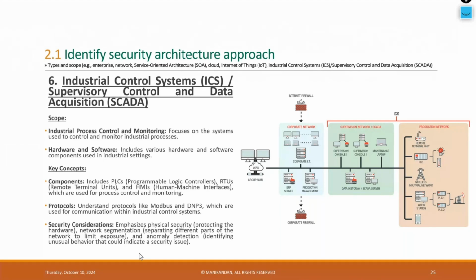What sort of measures shall be taken in Wi-Fi? When we are talking about industrial Wi-Fi, we have to make sure that only authenticated users are allowed, and their authentication should be done with LDAP or Active Directory. We must also cover how to secure remote access for OT devices. We shall wait, I'm coming to that question only.